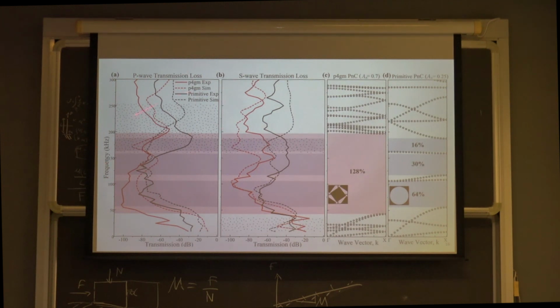And probably you're wondering about these dotted areas here on the plot. At these dotted areas, we cannot trust the experimental data, and actually they have significant disagreements here, right? This is because of the ultrasonic transducers. We use 100 kilohertz transducers, and they don't perform well for the P wave at 200 kilohertz, and for the S waves at around 170. And also here at the bottom, you can observe discrepancies, right?